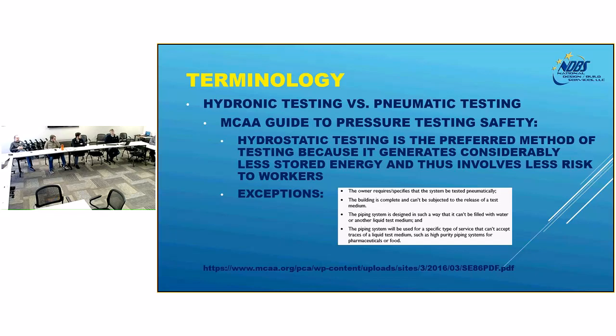So when I worked at the chemical plant, and most manufacturing plants that you work in, they do not allow pneumatic testing because of the safety concern. So I wanted to mention that, and for the purpose of the rest of this presentation, I'm not really going to talk about pneumatic testing. It's all going to be hydrostatic testing based. It's worth noting the exceptions.